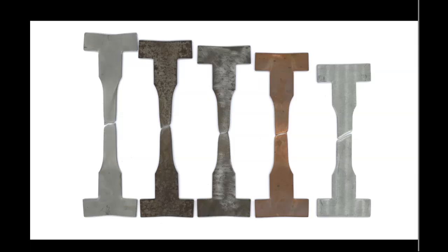So normally the descent from the peak to the fracture, brittle materials have very, very little descent curve. So from the ultimate tensile strength to fracture, it's rapid and quick and very low movement. While ductile materials, normally they will elongate, start necking, start shrinking, and then fracture. Okay, if you could catch that point, that will be great.